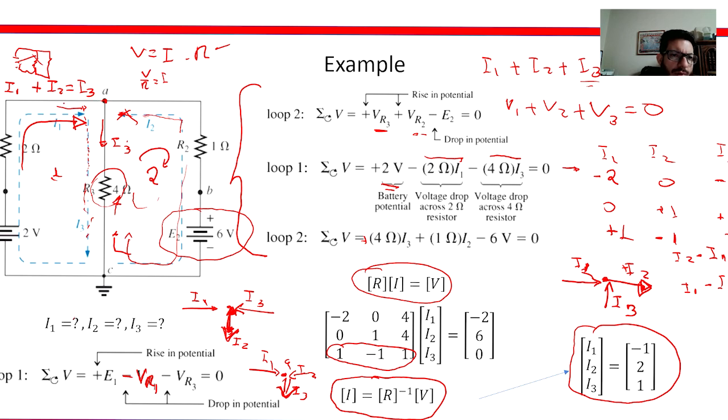And all you need to do is set up your equation of voltages so you have as many equations as unknowns. So we have three currents and three voltages. We need three equations. One equation comes from one mesh, one loop. The other equation comes from the next loop, and the third equation comes from the conservation of charge. So the only difficult part here is realizing which direction we should keep the loops.